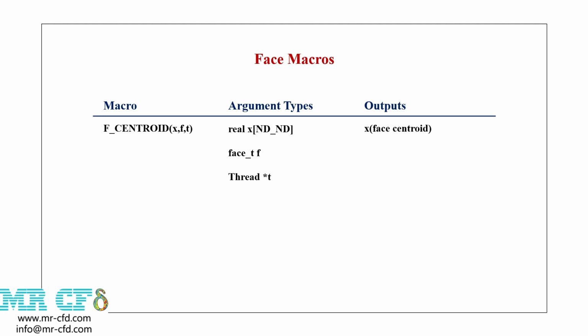The F-centered macro represents the coordinate of the spatial position of the center of the desired surface. This macro consists of three arguments. The first argument represents a variable that receives the spatial position coordinates of the desired surface. In fact, when we have a surface, its x, y, and z components have a certain range. The values in this range are received in a variable named x, so that the mentioned macro can find the median value of each of these ranges.